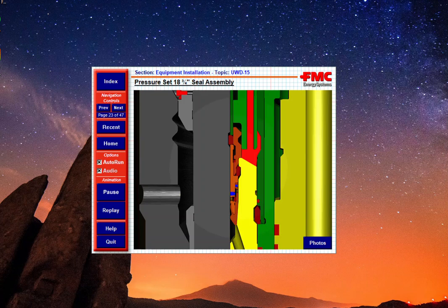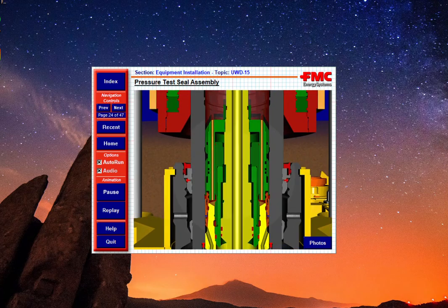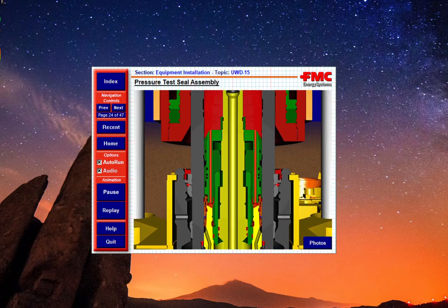The primary sealing element of the assembly is the straight bore metal seal, or SBMS. These are high-pressure metal seal bump profiles which seal against pre-designed metal seal areas on the casing hanger and wellhead. The metal-to-metal seal assembly used on all casing hangers is the same in all casing sizes. The seal assembly and BOP are tested by applying pressure on the choke or kill line against the seal assembly and a closed preventer in the BOP stack.